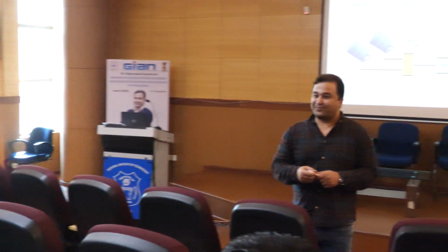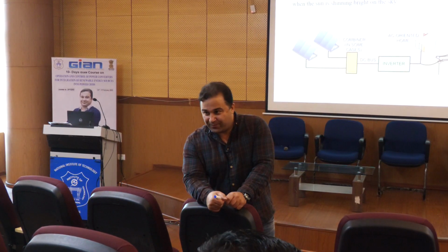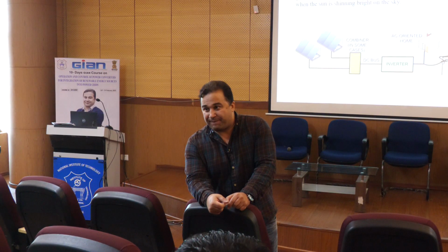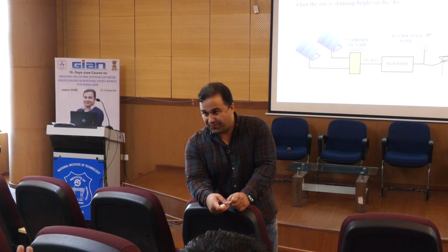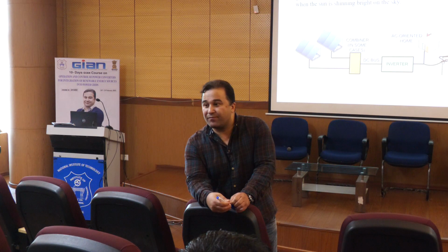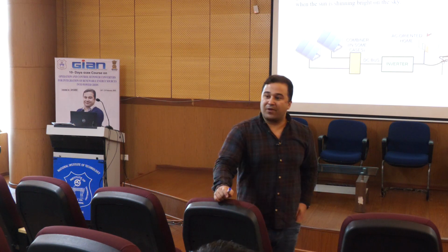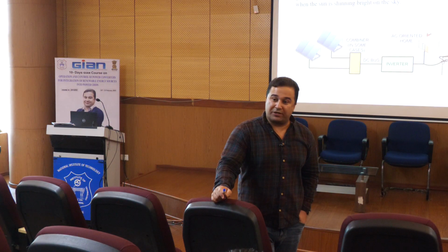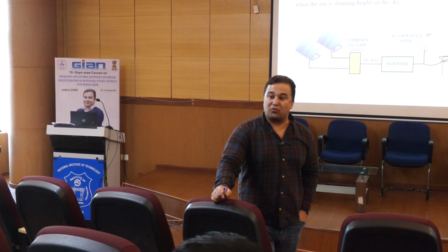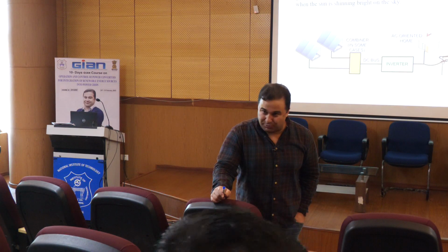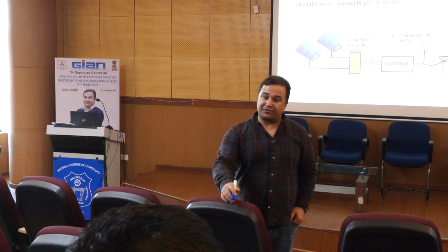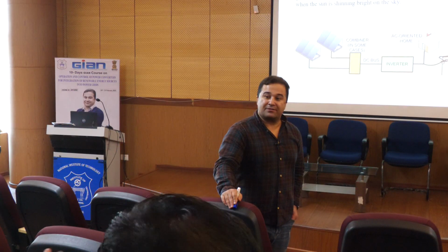The question was that, as you said, if it's disconnected from the main transmission line, the appliances won't work inside the home. But in our case, considering the light goes off, like electricity is off or it is turned off by the main station, still some of the appliances will be working, like an inverter. I said that if your controller is in a way that your inverter works as a voltage source, it is possible. But this one is not a voltage source, it's a current source. But we can store in the batteries and use that.